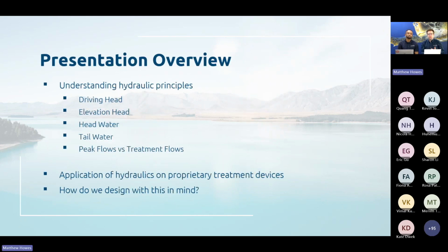So a little bit about the presentation, what we're going to cover today. We'll start off by understanding the basic hydraulic principles. We'll define what driving head is. We'll define elevation head or physical drop through a device. We'll look at what headwater and tailwater are and how they impact both on the treatment device and how the treatment device impacts onto the network. We'll look at peak flows versus treatment flows and how we manage those large rainfall events, the likes of which New Zealand is currently getting a fair bit of.